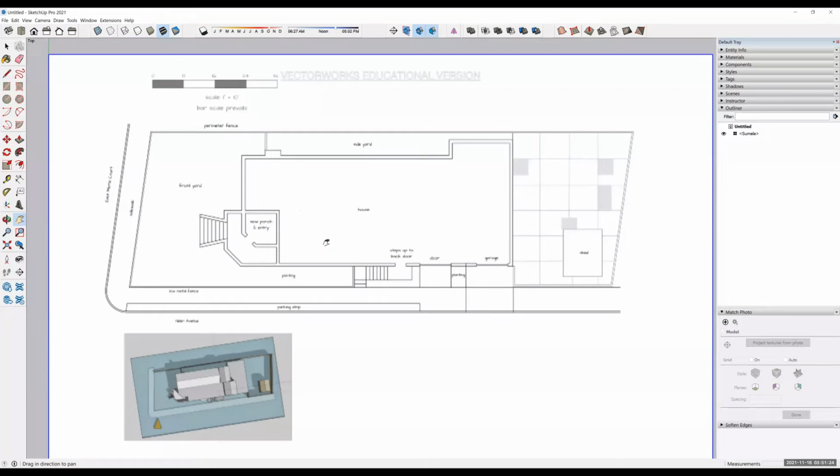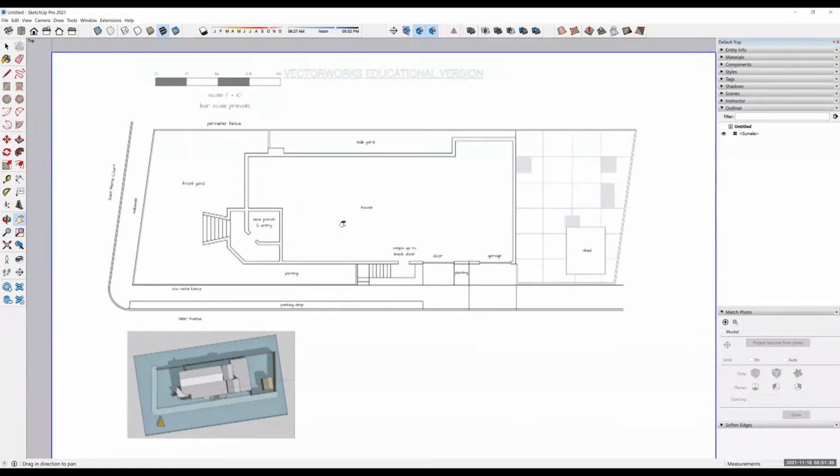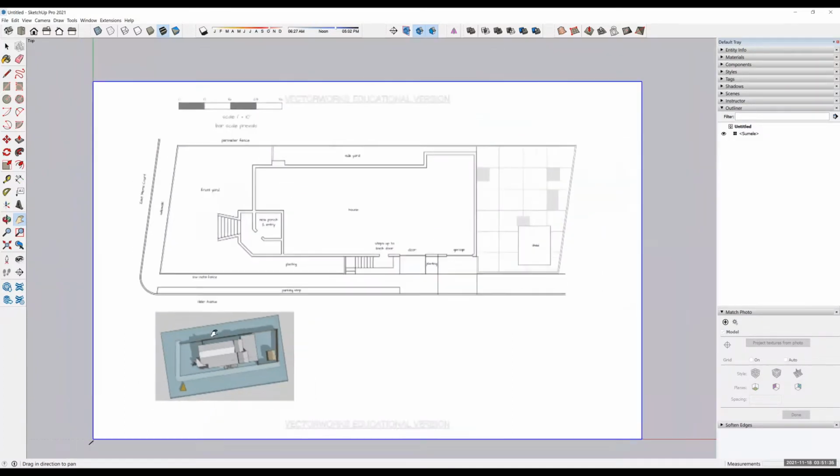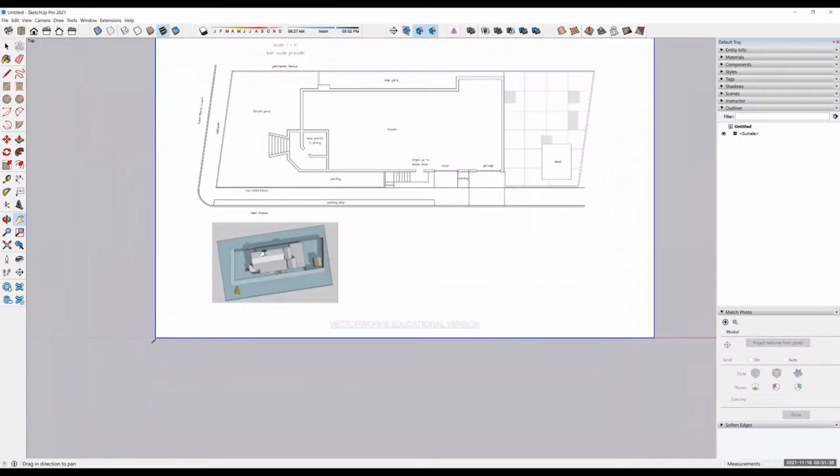And second, you want to rotate this map to the correct, true north orientation. That's how it can create a shadow study. You see the true north. This is, I believe, the north arrow. You should align the north arrow. Based on this context map, I can tell the north arrow is actually aligned with this street rather than the building.